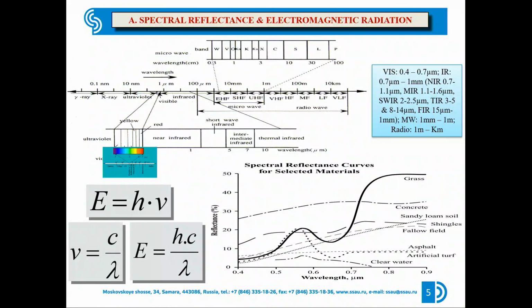So, here is too much information, but as we are human beings we cannot see the infrared region. So, we give some color to infrared to read the information. That is why a satellite image is always called FCC, which means false color composite, because they are not true color. One more thing: in water, in the visible range it has some reflectance, but if water is clear then in infrared there is no reflectance. That is why in a satellite image water always looks black.